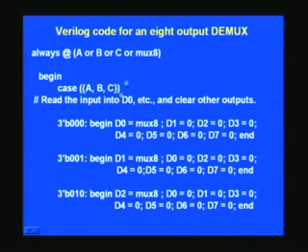And what it does here is it reads mux 8 as the input, and then depending upon the ABC inputs, it assigns it to the particular output that you decide. For example, if it is 0 0 0, we notice that mux 8 must be routed to the D0 output as such. So, that is precisely what is being done in this statement. So, mux 8, which was the output of the 8 input multiplexer we have seen earlier, is assigned to this D0 here.